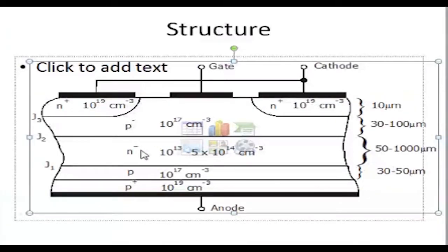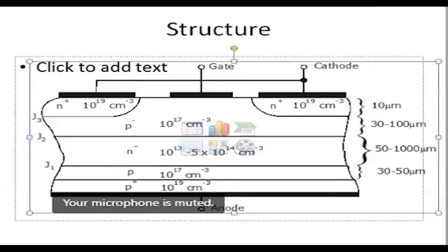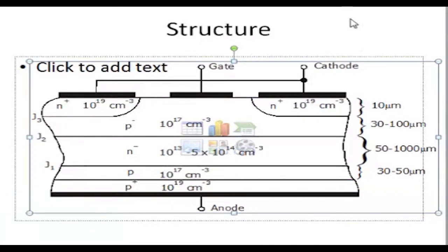I think everyone can see this figure, right? Based upon this, we can understand. Next, you can see the different voltage ratings, different SCRs. This is one SCR. Normally, we use this type of SCR in our laboratory. This is the SCR that is used for HVDC systems. Various ratings of SCR are available in the market. Voltage ratings are of 10 kV RMS value. Current ratings are of 30 kiloamperes, for a maximum handling capacity of 30.